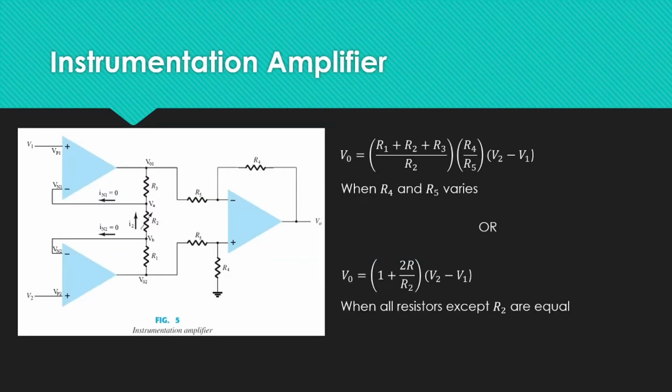So, moving on to the last topic, the instrumentation amplifier. A circuit giving the output based on the difference between two inputs times a scale factor. A potentiometer is provided to allow adjusting the scale factor of the circuit. While 3 op-amps are utilized, a single quad op-amp IC is all that is essential, other than resistor components. So the instrumentation amplifier is suited perfectly for detecting and amplifying a small signal deviation when superimposed on one or the other two of much larger and otherwise identical signals.